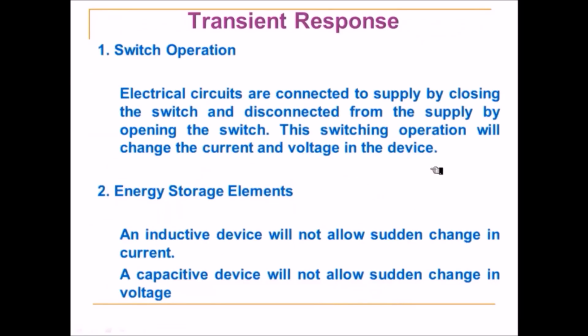What is the reason behind the transient response? Why do circuits show transient response? There are two important reasons. One is the presence of switch in the circuit, and the second one is the presence of energy storage elements in the circuit.